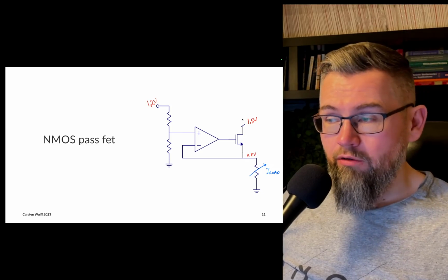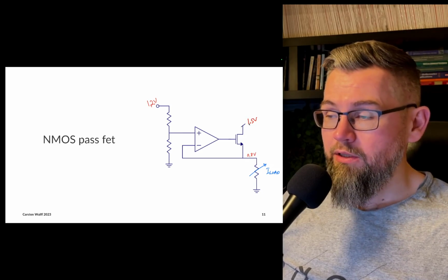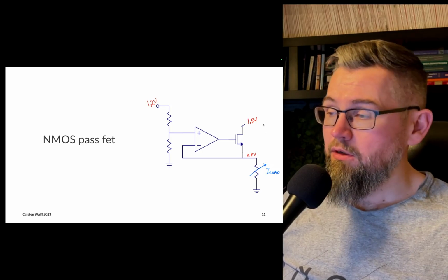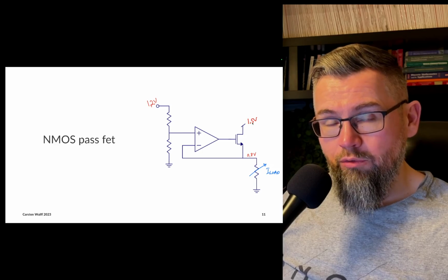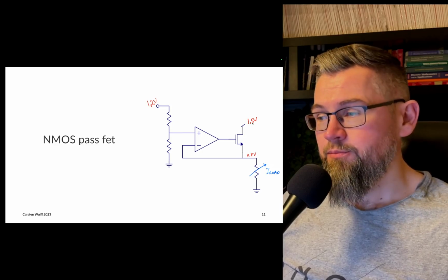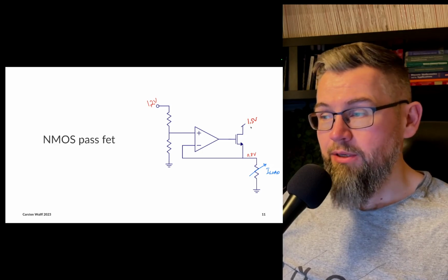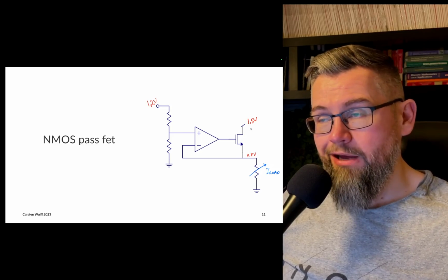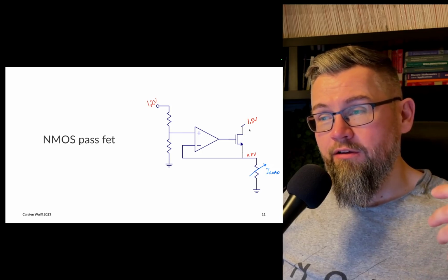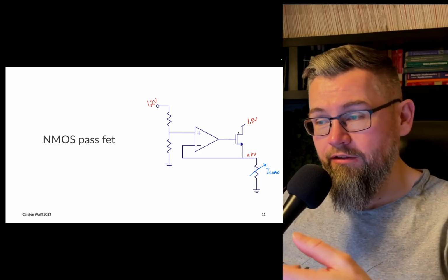However, from the power supply or from the battery, we are consuming the same current, 10 milliamps, but then we multiply it by 1.5. So we're using 15 milliamps from the battery, and maybe even more if it's pulled from a 4.3 volt battery supplying the IO rail, supplying this regulator again.